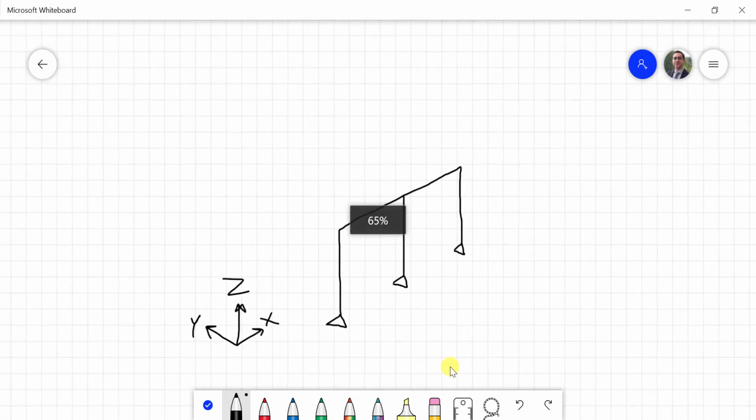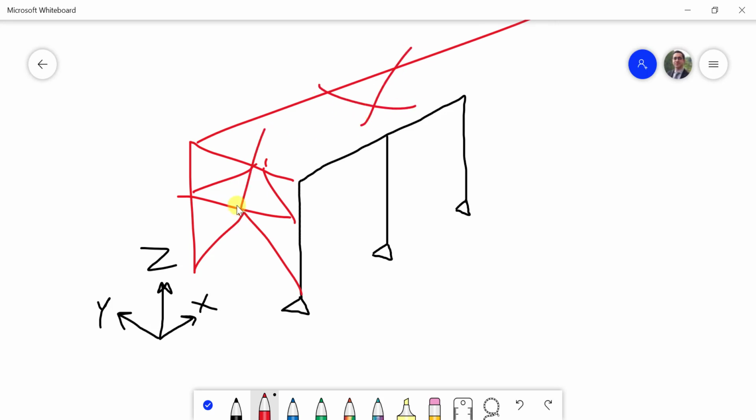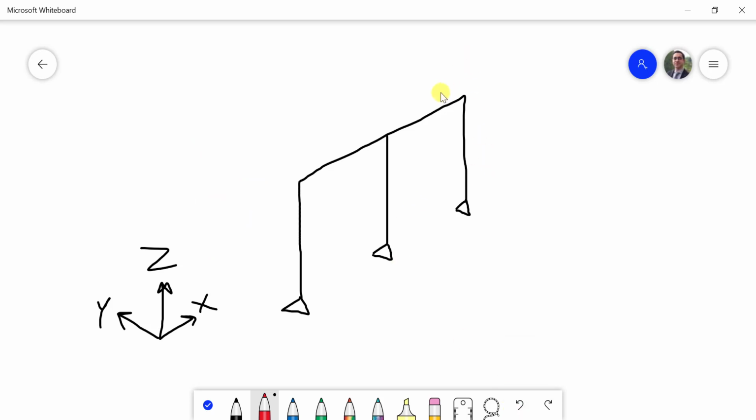Okay, so look at this example that I'm displaying here. Let's assume that after you drew the 3D frame, the entire thing that we just did, you said, you know what, I don't care about all these elements, I will just remove them, delete them, and just keep the planar moment frame, which accidentally has some pinned connections in this direction, meaning that the frame is allowed to rotate about the x axis at the supports.